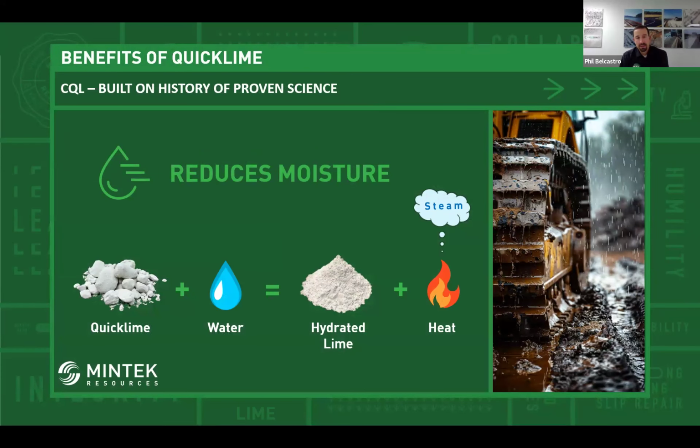Like I said before, it wouldn't be a Mintek presentation if we didn't say dry, modify, stabilize, right? So we're still going to dry. Still going to chemically combine with that water. We're going to lock it up, creating the hydrated lime in the soil. Exothermic reaction, going to generate some heat. So cold days are coming. We're going to drive off some additional moisture in the form of steam. I'll stop there on the cold days. I think I'm coming back to that later, getting ahead of myself.